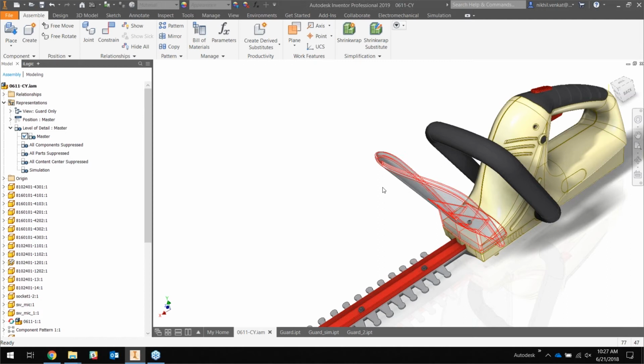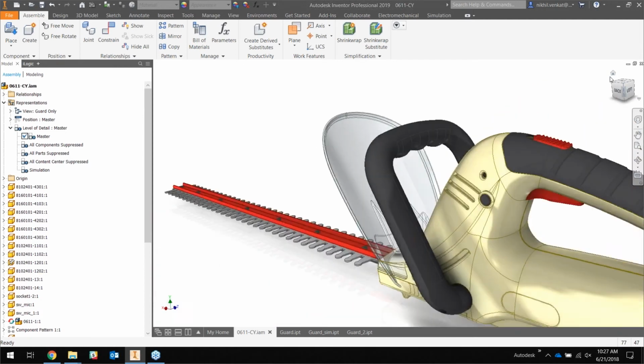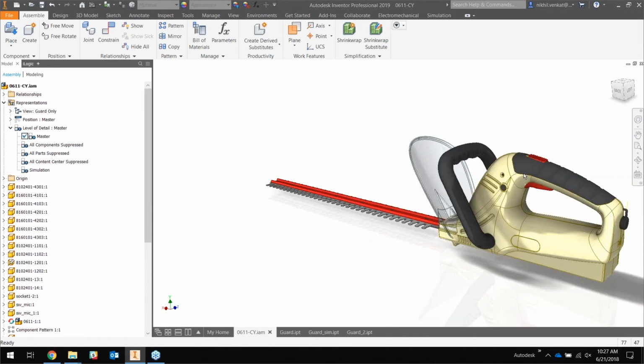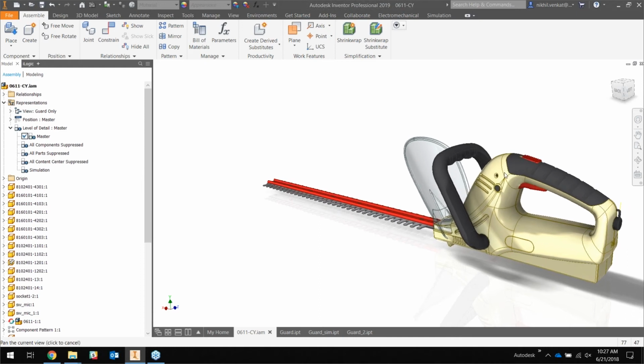Yeah, and I'll just add something to that too. Generally when we're looking at things like this, we want to get an idea of how it's behaving and a general approximation of what the actual object is seeing. So you can simplify the problem a lot in that case. And sometimes when you do simulations like this, you want to simplify some parts, some bodies, because sometimes the geometry doesn't lend itself well to the simulation, or it'll overcomplicate things, especially on the mesh side of things. So it's just a simplification of the problem, pretty much.